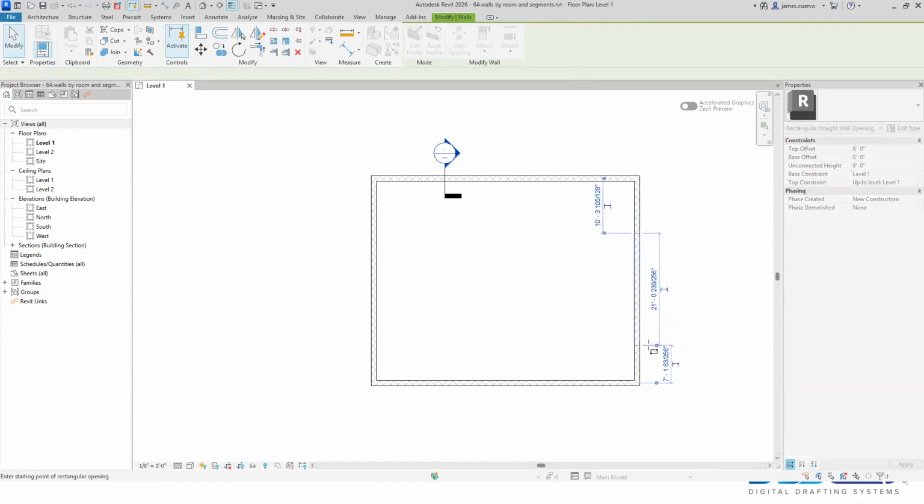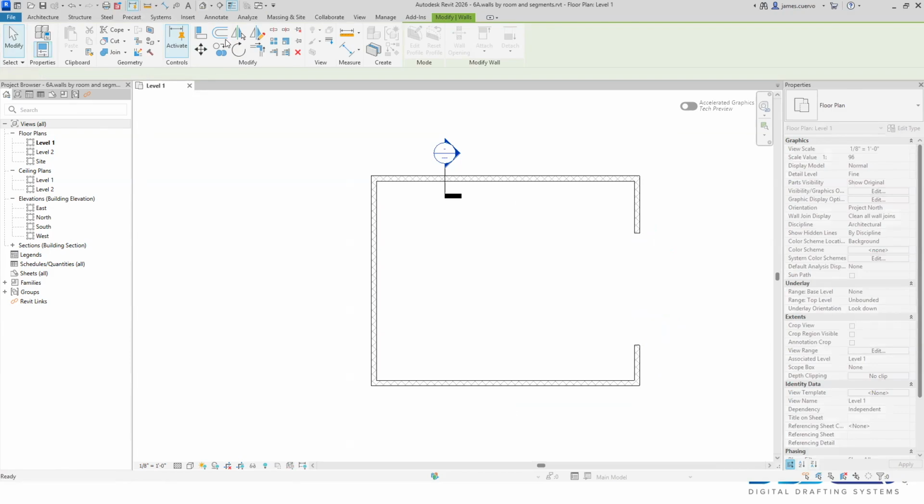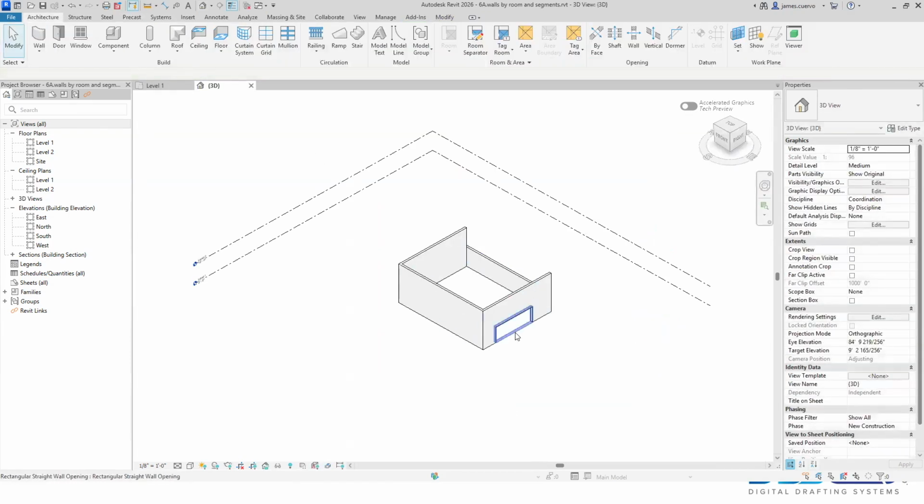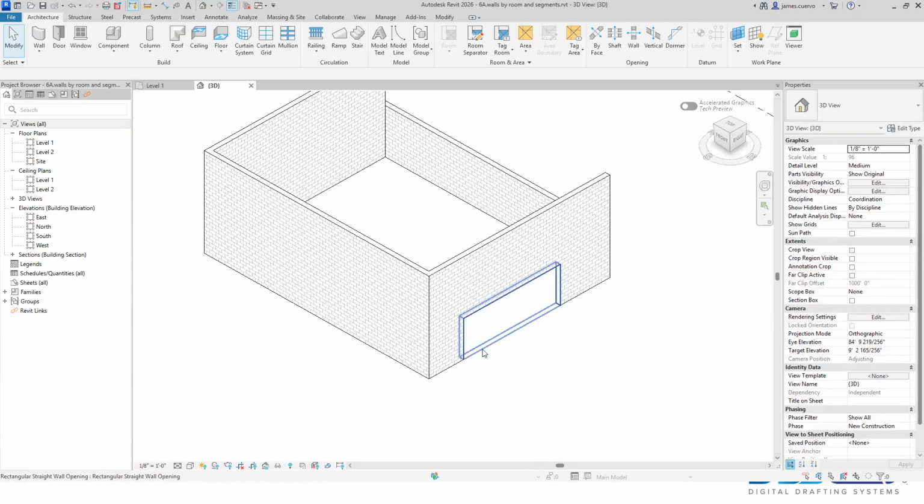Okay, and that's our opening. I'm just going to go ahead and create a 3D to make sure that, first of all, my room opening goes to the floor. The one thing that I would like you to please remember is that when anything is defining a room, it's actually based on the floor plan. It's not based on the ceiling. It's not space. It's on the floor plan.